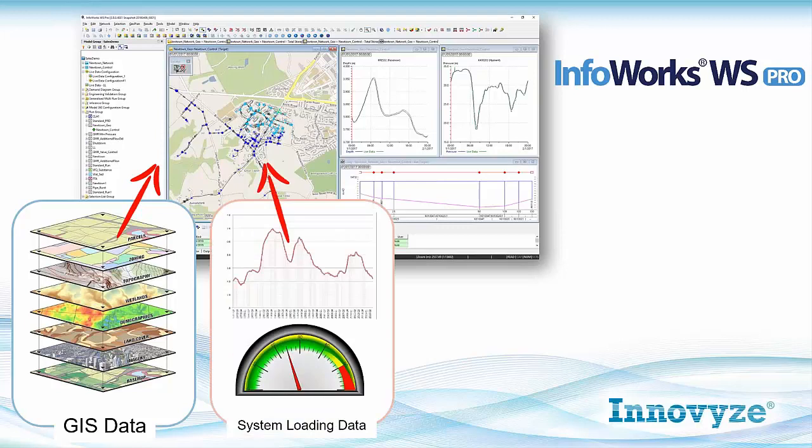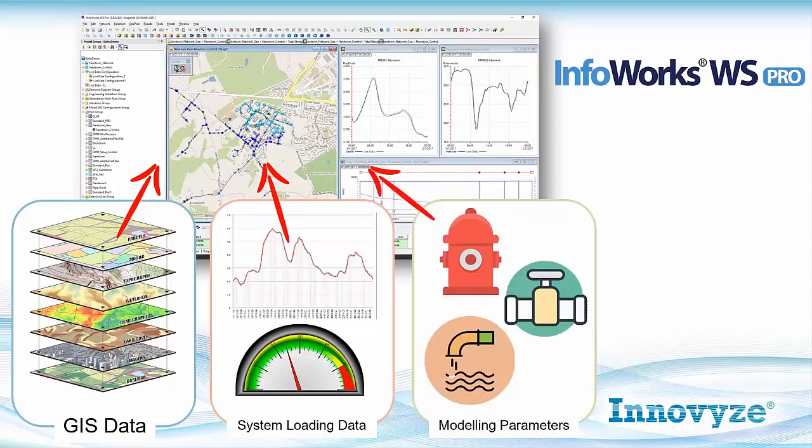We could also use some system loading data that we can get from our clients, like flow metering and water consumption records, or we could use estimates from customer characteristics like population data or land use data. We then apply some modeling parameters like pipe roughness, just to mention an example, and by doing that we have a working model that we can calibrate and then use to support our understanding of the behavior of the system. But the question is, what do we use the hydraulic model for?